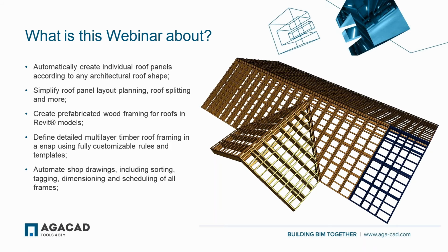So today I'm going to talk about how to automatically create individual roof panels according to any architectural roof shape, then how to simplify roof panel layout, planning and splitting, then how to create real prefabricated wood framings in the roof models, then how to define detailed multi-layered timber roof framing, and then how to automatically make shop drawings, including sorting, tagging, dimensioning, and scheduling of all the frames.